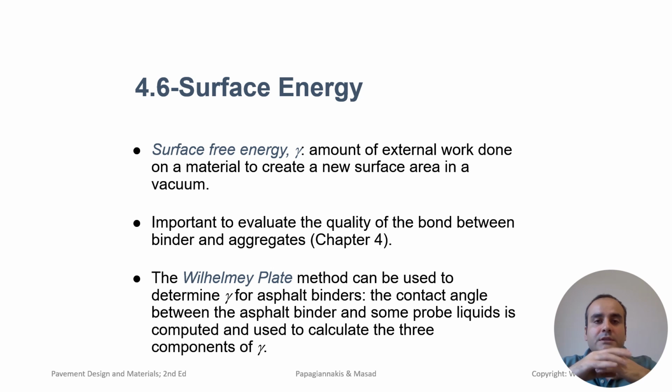Usually, surface energy is measured using techniques like contact angle measurements and surface tension testing. The Wilhelmy plate method can be used to determine surface energy for asphalt binders. In this technique, the contact angle between the asphalt binder and some probe liquids is computed and used to calculate the three components of surface energy.